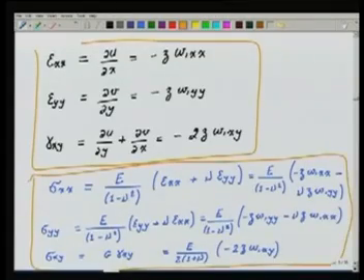Now we are going to use the total potential energy. We are going to write the total potential energy expression in terms of the state of stress and the displacement given to us. W is not known, but we will write it in terms of W. And then how are we going to obtain the equations for W? By saying that the solution W is the minimizer of the total potential energy. So here we are using the approach of the variational formulation. We could have used the principle of virtual work, or we could have used the differential equations to get to the weak form.